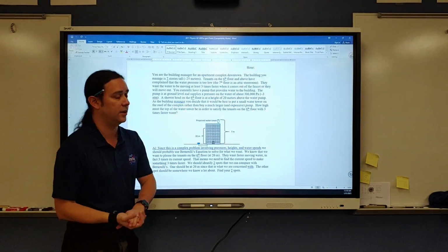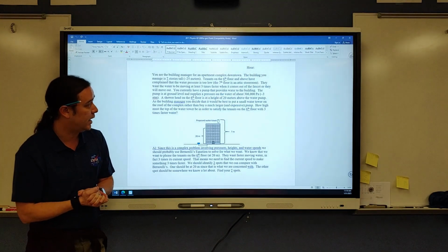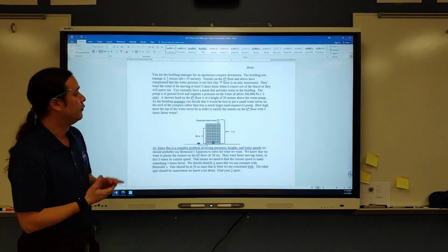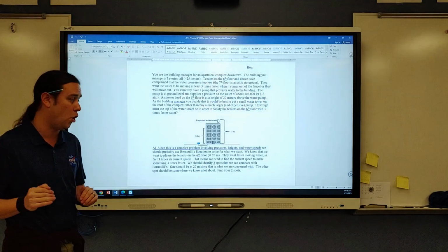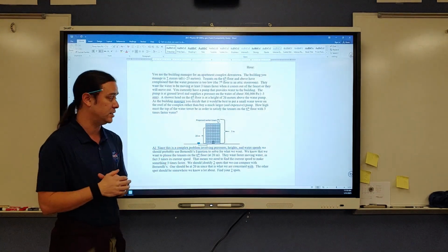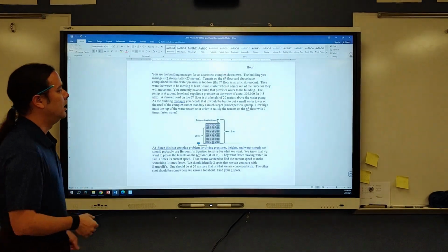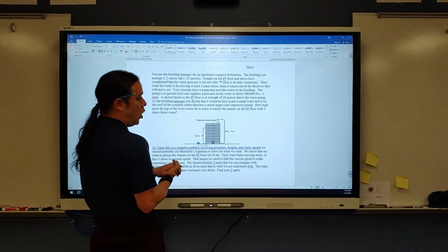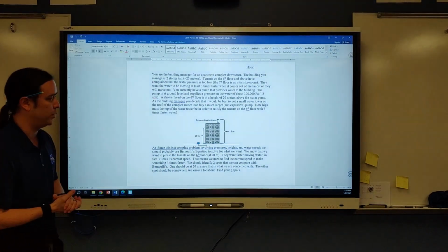I've given us the goal of saying that they want the water speed, when they turn on the faucet, to be about 3 times faster when it actually comes out of the faucet than it currently is. Right now, and this is not uncommon in a tall building, you would have a water pump that pressurizes the water so that it can be sent up to the higher levels, as we're going to see as we apply this Bernoulli stuff. In this case, the pump at the ground level is supplying a pressure onto the water source of about 306,000 pascals. That's about 3 atmospheres.